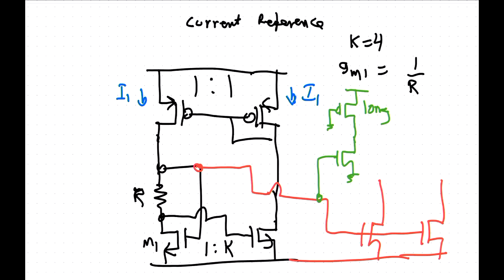So now you have a digital signal that detects the state of it being wrong. If it's high, it's wrong. So you can just pull out current somewhere, maybe like this. In this node here, for instance, there's many ways you can do it. So if this is high, this is the logic state that says it's off. So that's high. We now pull out current in this current mirror here. That's going to force current in, so that is going to boost this up, and the positive feedback is going to keep it going. This is going to go high, pull this node down, that's going to go off. So that is a very common way to deal with that problem. So, startup circuit.